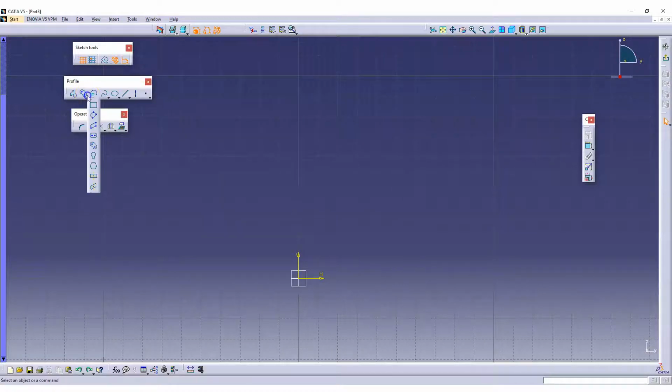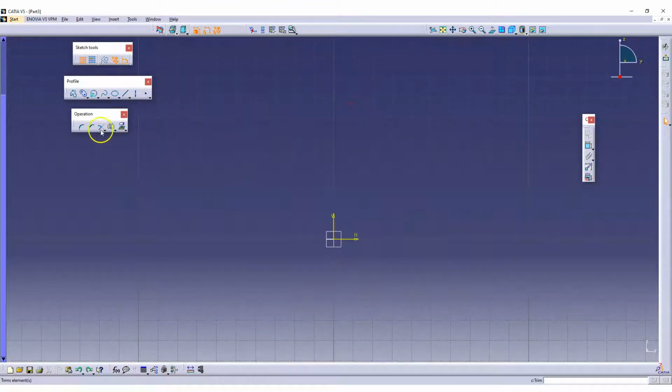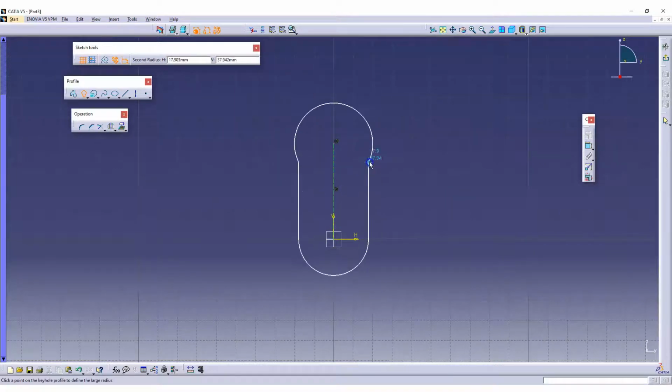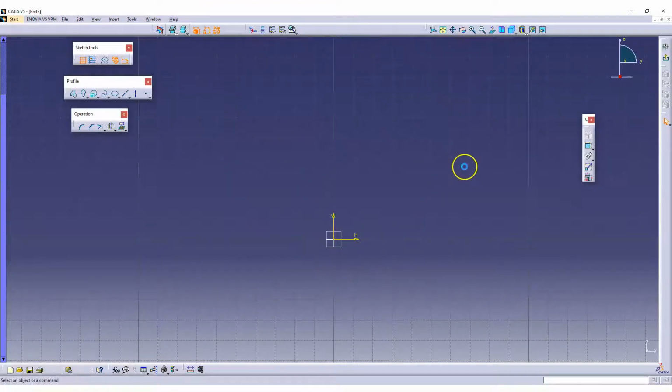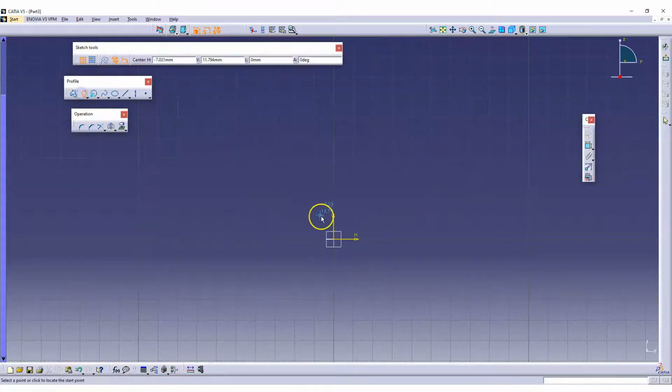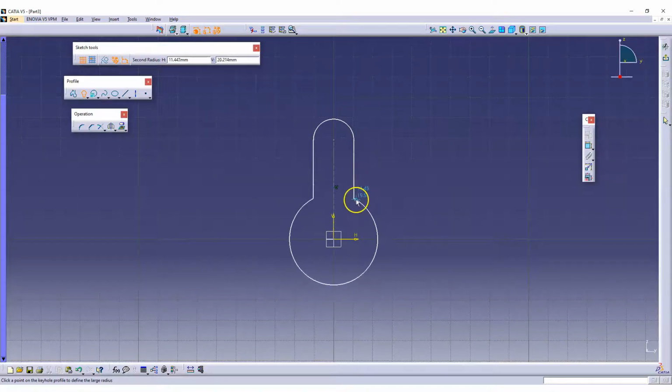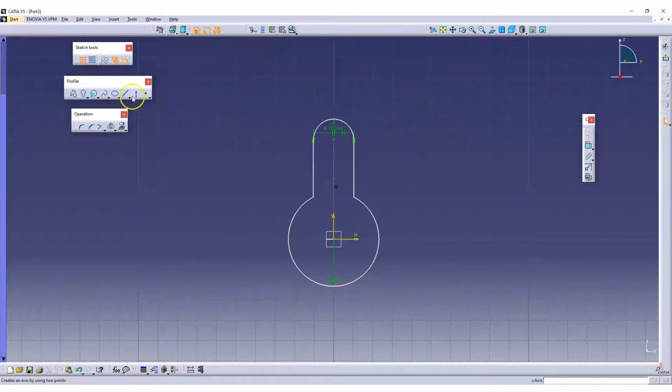Then we have different formats, pentagon, hexagon, keyways. You can just create your keyway as well, right? You can just even create your keyway as well. Just create this keyway. Just see this. I'm going to just draw this one, and you can constrain this one. All these dimensions can be constrained. Just draw this one. A ready-made command. So this, you can just create your keyways. All this is happening because of this one, right?